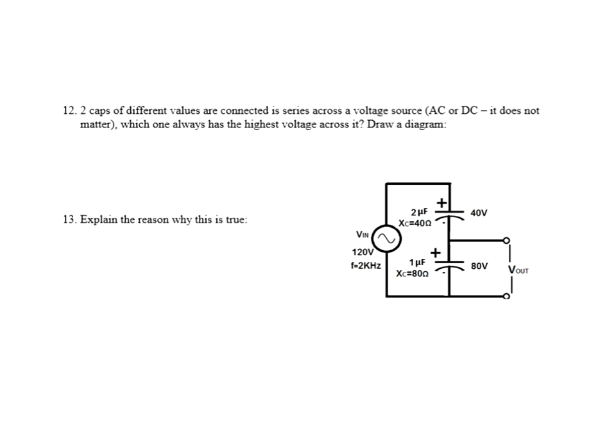In the field, the application of this would be such that if you have to replace a capacitor that's in a series bank, you would always want to make the smaller capacitor at least equal to the working voltage of the voltage that is applied. Because the smaller the capacitor, the more voltage of the source it will gather.